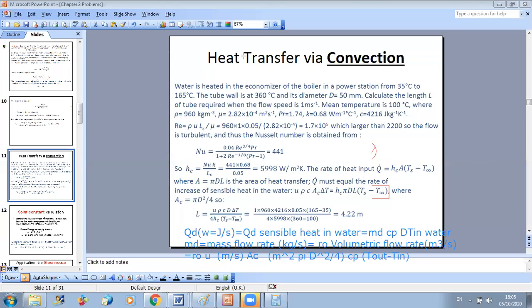When I studied such courses, they gave us several possibilities for the same type. You can work with this, or this, or this. But based on experience, they say maybe in this range it's better to work with this empirical relation, and in another range, the following relation is better. So even if it's turbulent, a relation can work better in certain zones. Reynolds number higher than 2200 is a very wide range, so some empirical relations can work better in certain Reynolds zones than others.